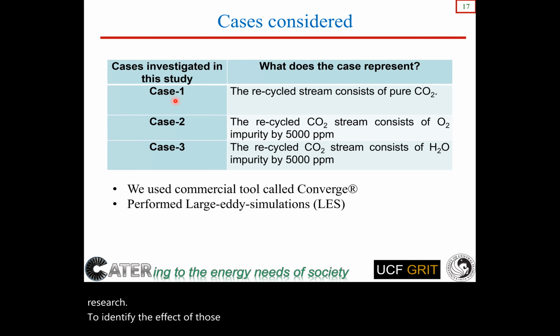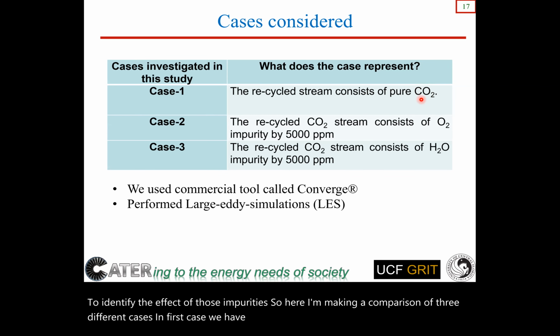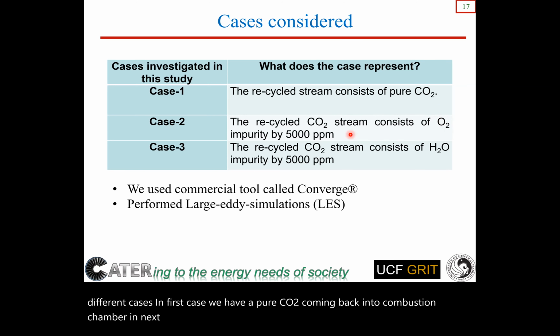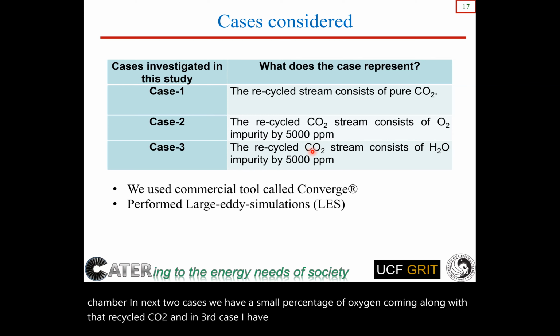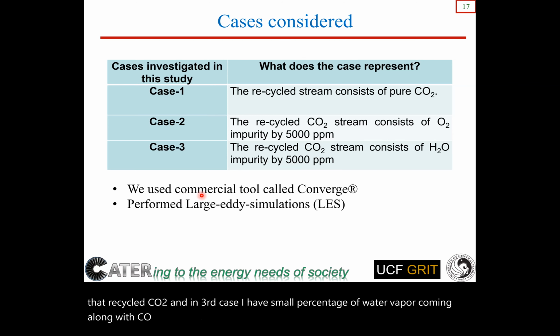So here I'm making a comparison of 3 different cases. In the first case, we have pure CO2 coming back into the combustion chamber. In the next 2 cases, we have a small percentage of oxygen coming along with that recycled CO2. And in the third case, I have a small percentage of water vapor coming along with CO2. We used a commercial tool called Converge and performed large eddy simulations. These are high fidelity simulations.